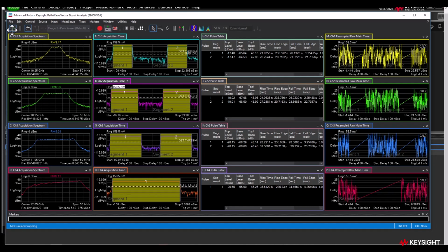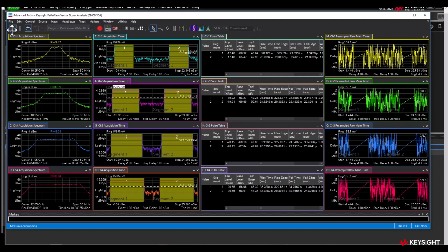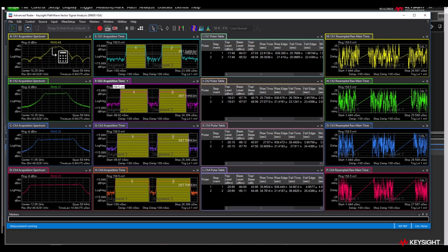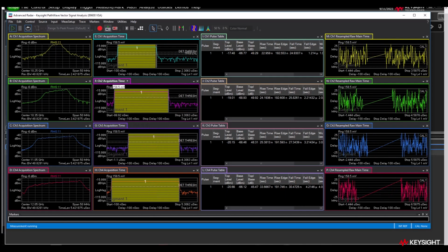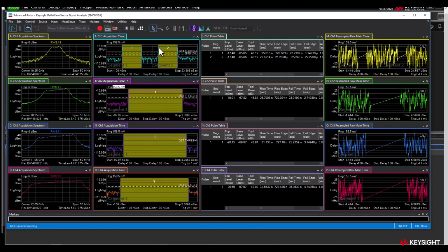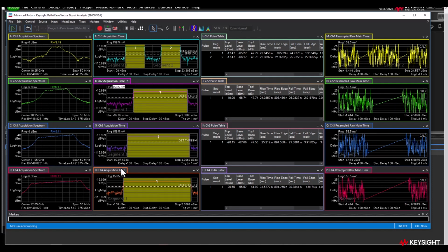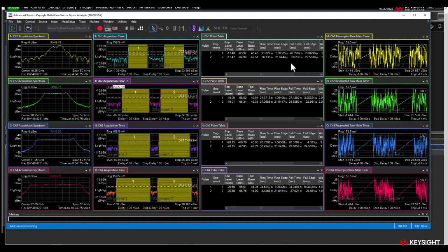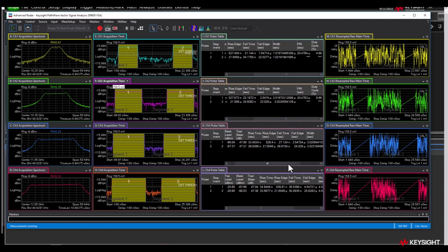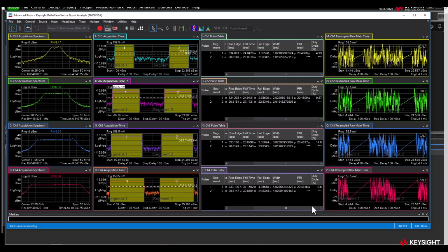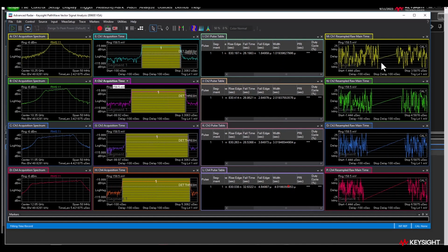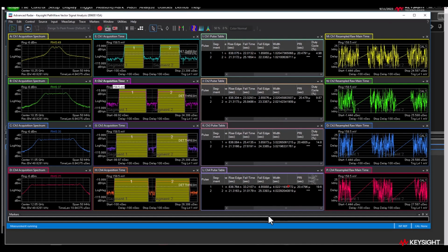We're also using the variable length segmented capture. So it's pulling these pulses into these individual segments. You'll see the 10, 20, 30, and 40 megahertz wide linear FM chirps. These pulses you can see that are being measured here. If we look across, we should see the different pulse widths as these are being separated out by each channel, tuned to them. There's your 1 microsecond wide, 2, 3, and 4, and here you see the linear FM chirps on each one of these.